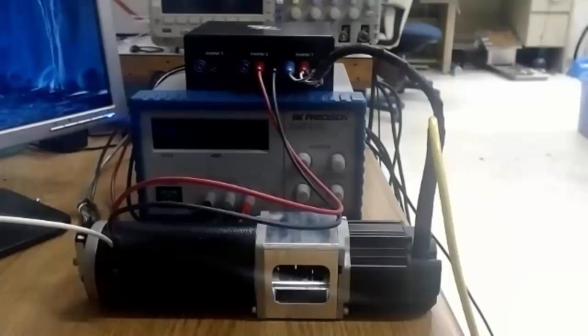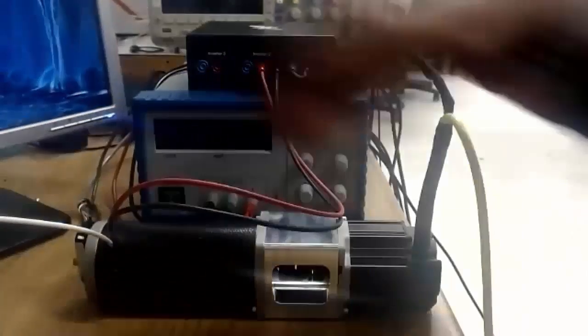The power rating of this motor is almost thrice that of the induction motor that we saw earlier, and the size is almost half to one-third of the induction motor. In general, a permanent magnet motor of similar rating as that of an induction motor would be somewhere between 1/4 to 1/8 the size. So let's go ahead and run this system.